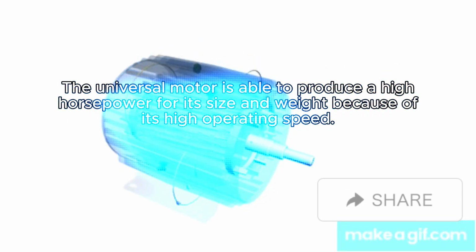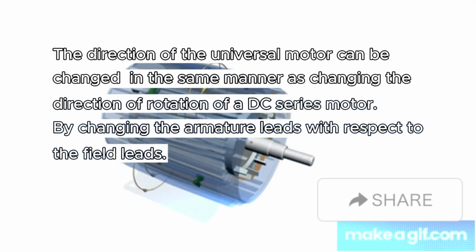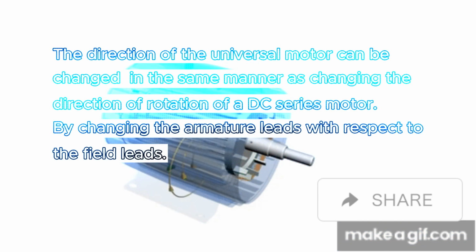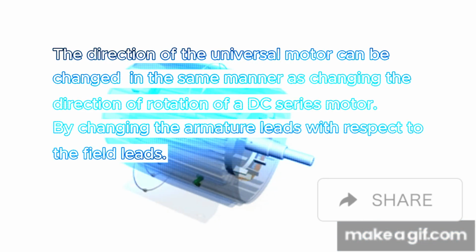The universal motor is able to produce a high horsepower for its size and weight because of its high operating speed. The direction of rotation of the universal motor can be changed in the same manner as changing the direction of rotation of a DC series motor, by changing the armature leads with respect to the field leads.